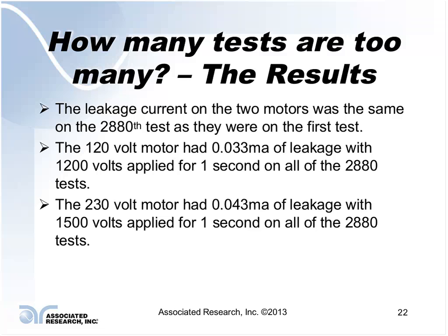It just so happened that at sea level, the test potential being applied was not high enough to jump that gap, but at 5,000-foot altitude, it takes less voltage to jump the same distance, and there it did create a failure.